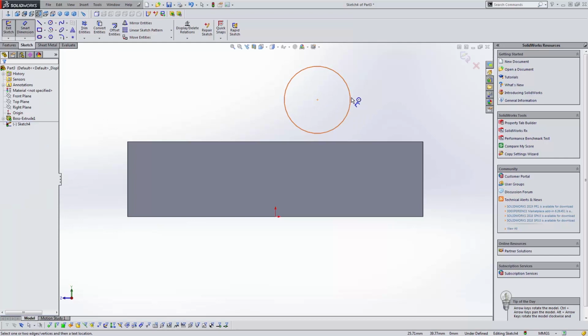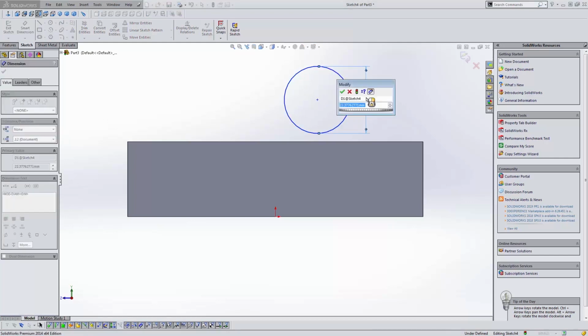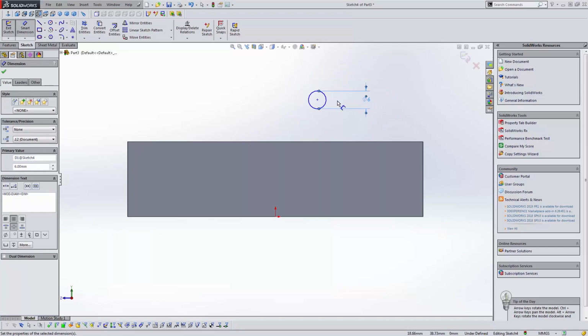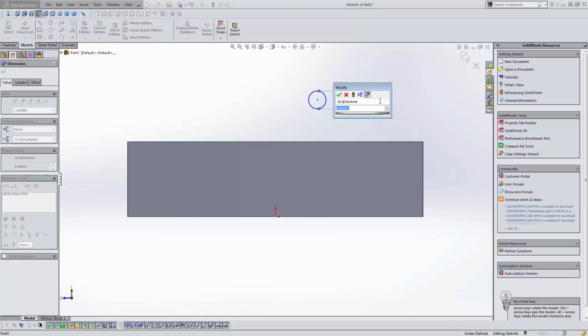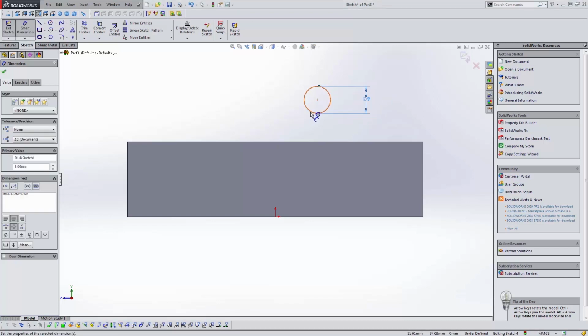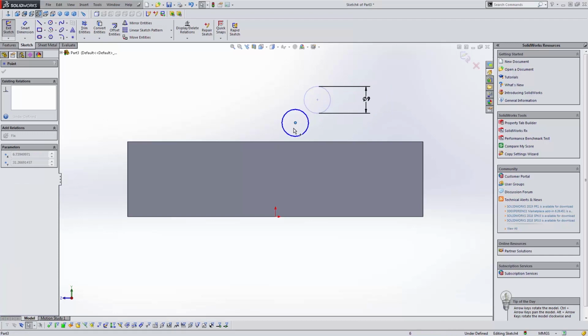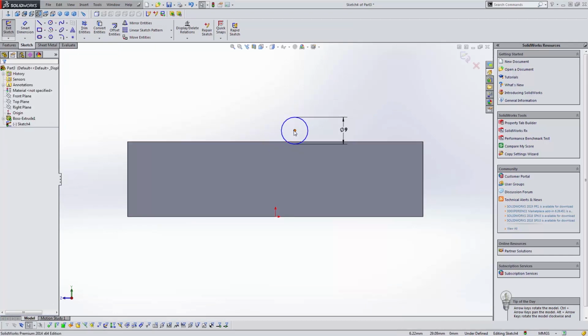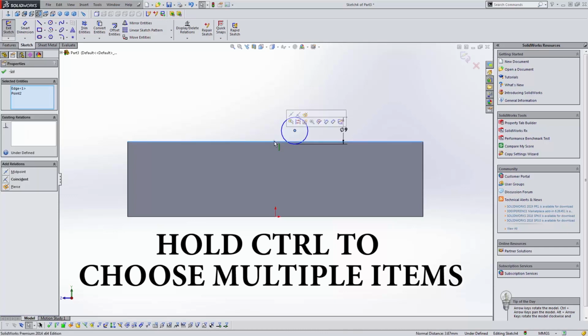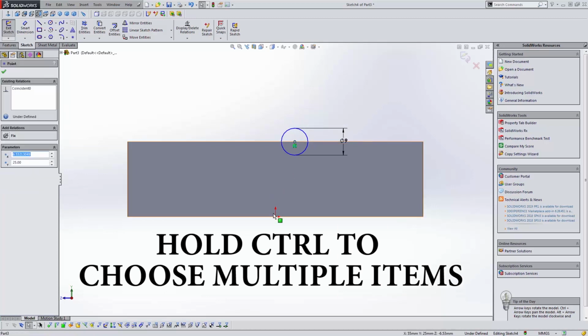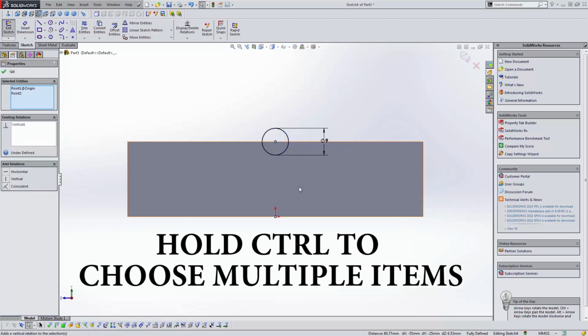So I draw that, and a pencil's probably like 6 millimeters, so I want the diameter of this to be 6 millimeters. That's probably about right. I'm probably totally off there. It's probably more like 9 millimeters. And then I'm going to bring this sketch, and I want it to be on this line here. So if I choose that center point, hold Control, choose that line, I'm going to say coincident, and then I'm going to choose that point, choose this point, and I'm going to say vertical.